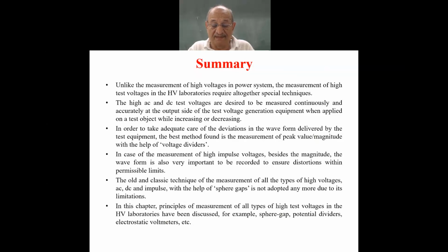Sphere gap is dying. Measurement with the sphere gaps is dying, but sphere gaps become like an ornament in any high voltage lab. Even in my high voltage lab in IIT Kanpur, we have a sphere gap available. We do use it for different purposes, for demonstration, for even measurement on very long gap in weakly non-uniform field. It can always be used. It's a classic instrument, you can say, or classic arrangement of two spheres facing each other.